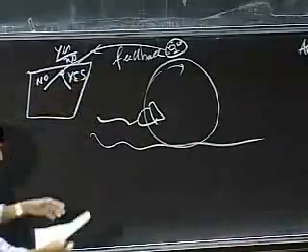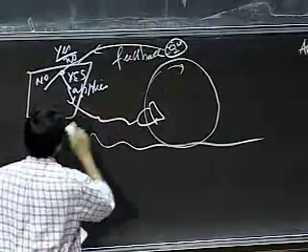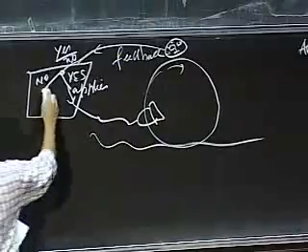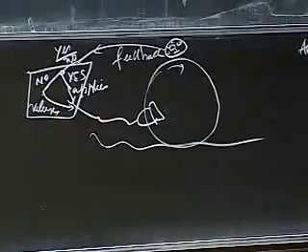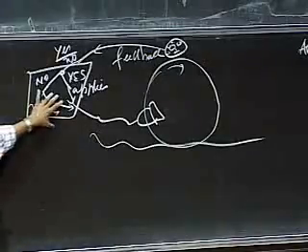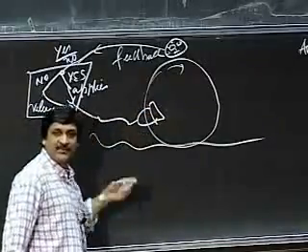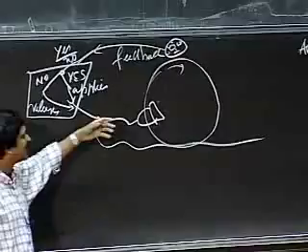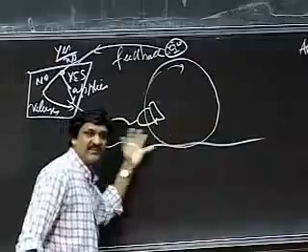If it's yes, then what this does is it applies the brakes even more strongly. It's turning, so I can apply more brakes. But if it says, oops, it stopped turning, the controller simply releases the brakes. And as soon as the controller releases the brakes, this one tends to loosen up a little bit, the tire starts turning again. So this way you're constantly keeping the tire in its region of critical friction so that it's constantly moving, and static friction applies to how hard you can brake. And it doesn't start skidding.